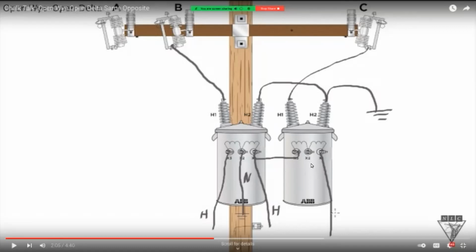Everybody still got lighting and power? Yeah. Lighting and power. They're in the same location every time facing the transformers. Lighting's on your left, power or high leg, either one, they both mean the same thing, is on your right-hand side.